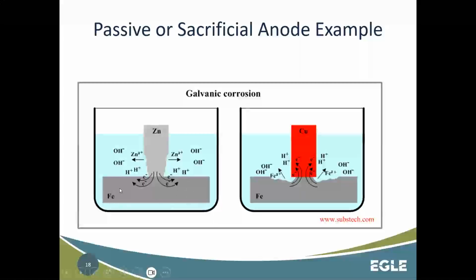But at the end of the day, we don't really care, because that's just something we're able to replace, where we're trying to protect this iron. Now, the converse, which would be a bad example in most circumstances, is having your copper versus your iron, where the iron is more likely to give off the electron than the copper is, losing that solid iron into suspension in the water.